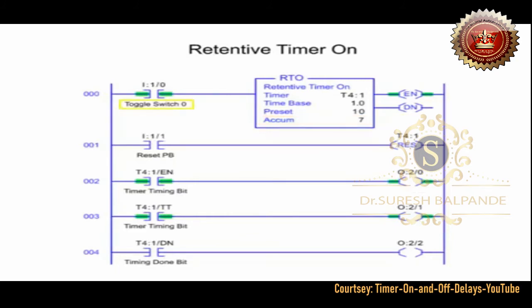By changing the rung condition to false in the retentive timer circuit, the accumulated value stops timing and retains the time recorded until the rung condition goes true again. As the accumulated value reaches the preset value, the done bit goes true and enables the output. A programmed reset instruction with the same address of the timer is used to reset the retentive timer's accumulated value.